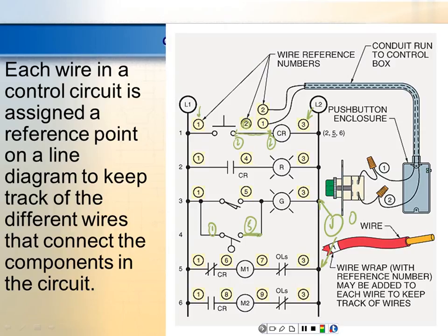It's electrically the same. So if I wanted to get across this limit switch, I don't have to get across that limit switch. I'm going to find L1 somewhere, and I'm going to find wire number 1, and I'm going to find wire number 5. You're going to say, wait, that's across the pressure switch. I don't care. It's also across the limit switch, right? You understand?